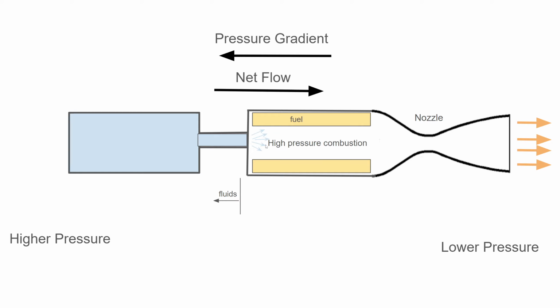But as we discovered before, in order to deliver the liquid oxygen, which is the oxidizer, into the combustion chamber, you need an even higher pressure upstream. So that's where the higher pressure liquid oxygen tank comes in. And the entire role of the fluids team is everything upstream of the injector. So it is our job to deliver the very high pressure liquid oxygen into the combustion chamber. The pressures that we're working with are about 50 times atmospheric pressure.